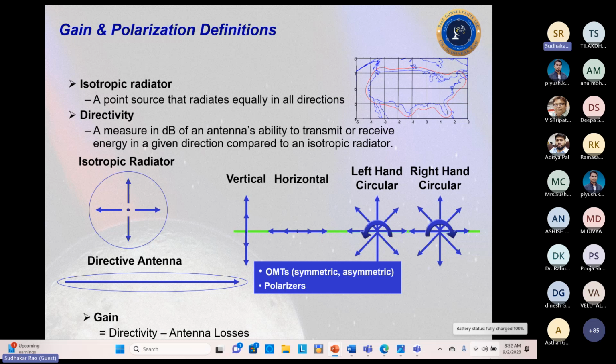So the sense of polarization is very important, because sometimes, in at least 3 cases, the polarization was supposed to be left-hand polarization, but it was designed for right-hand polarization, and people cannot use it because the ground stations are designed to capture the left-hand polarization. So they have to make some changes to the ground station. So this sense of polarization you need to measure many times during the test phase of the satellite.